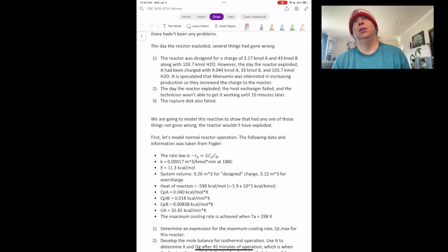In reality, there should have been multiple rupture disks. Probably the rupture disks should function differently. So some function from one phenomenon, others function from another phenomenon, and that way, if one type of phenomenon can't operate for some reason, the backup ones will come into play. So proper safety design would incorporate those things.